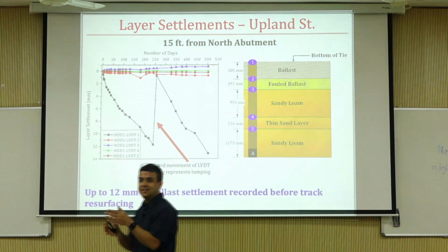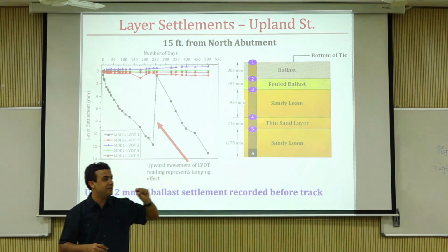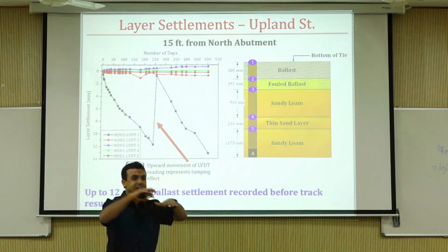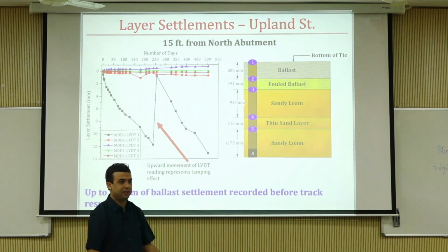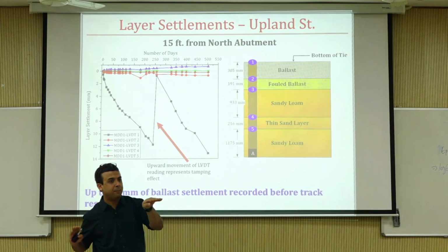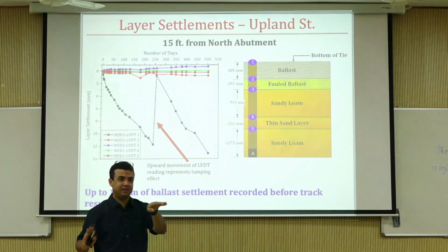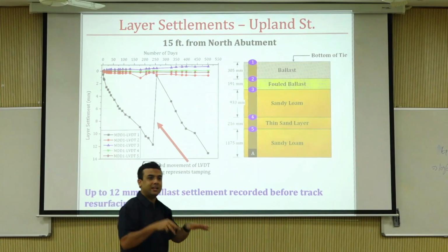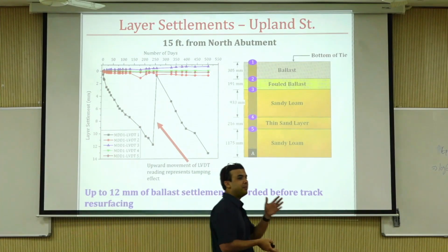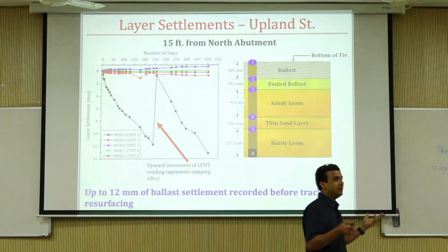It's differential settlement. There is always an elevation difference. Why does that happen? Because the bridge is standing on deep foundations. It's going to rock or something. It's not settling. And your approach is a fill layer or something, either an embankment or something like that, right? And that's going to settle with time. That's the permanent deformation. That's rutting, right?